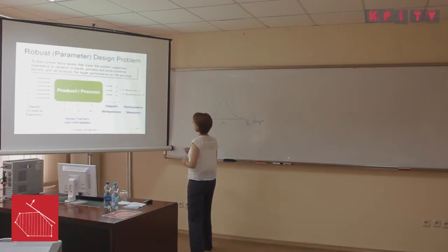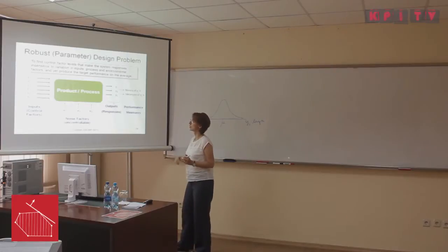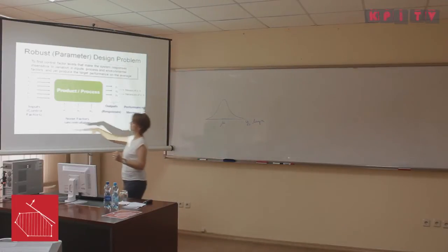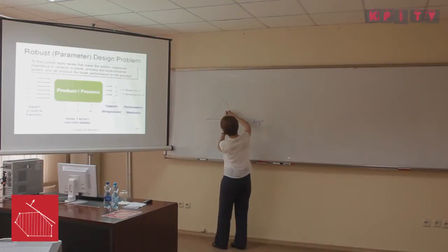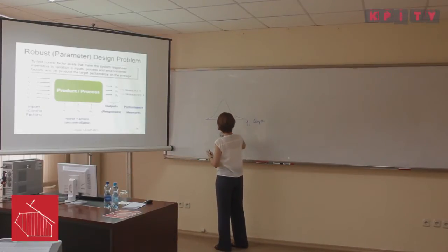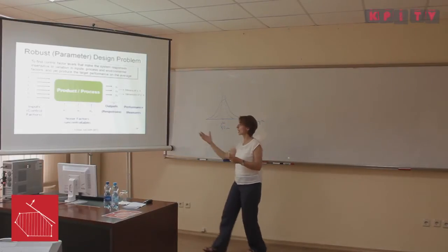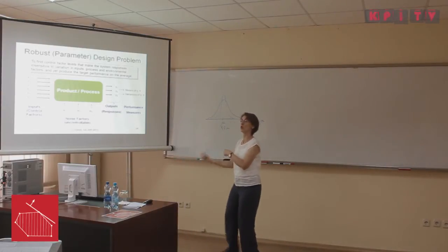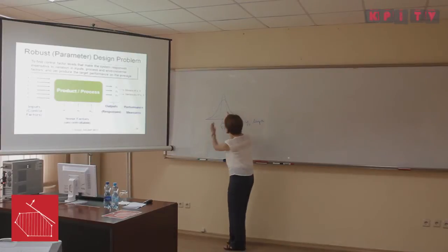So if we make an experiment with a process, let's say the pendulum cutting process, and we increase the speed of the conveyor, decrease the speed of the conveyor, make some adjustments on the machine. These are under our control, and we see if we can get very robust lengths, meaning we have the target length, say it is 50 centimeters long, but with very small variability. That's a robust process, meaning it has small variability, and no matter what happens in the cutting process, the conveyors get old or not, and the human error, operators make errors or not, still you have many of the pendulums cut very, very close to this average.